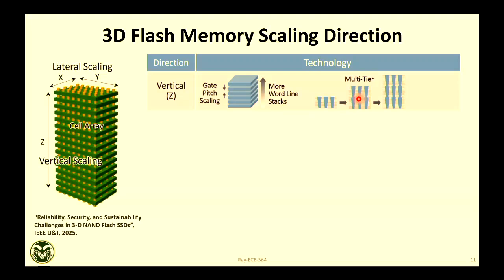But yes, you again grow this, and that will increase the cost, because the process time will be repeated. It takes a couple of hours to grow this, and then the same hours you have to use to grow that. The process time will be higher, and more than that, fundamentally your temperature budget will be limited. You can grow the bottom layer with a higher temperature budget, for example, say 300 degrees centigrade.